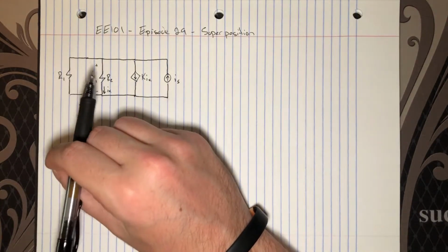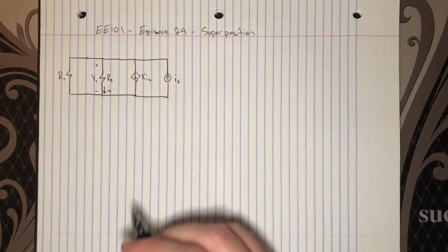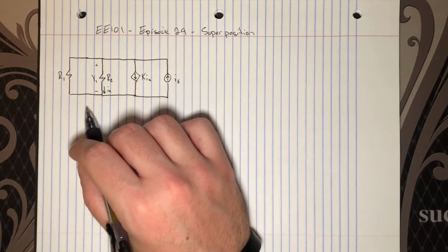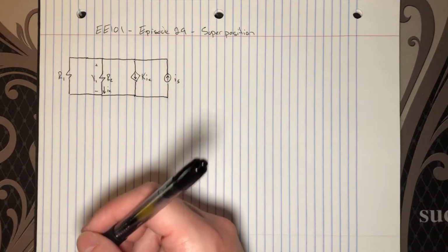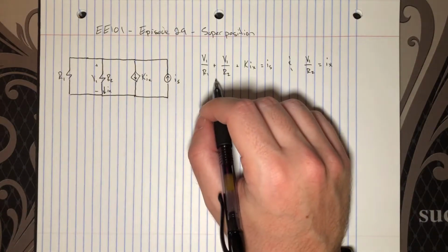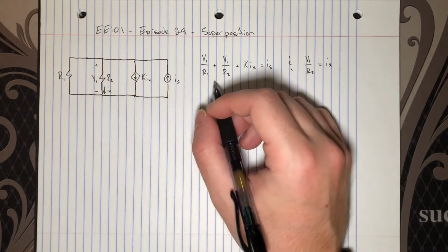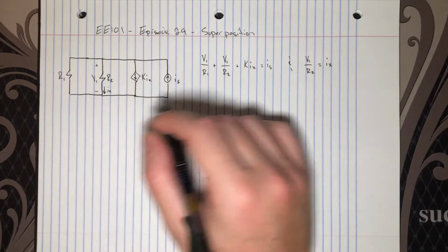I'm calling the voltage across R2 V1 because I'm counting up independent responses to sum via superposition for the total response. So for this first subvariant, I'm just going to call it V1, and in the next circuit I'll call it V2. So I'm going to solve for V1 in pretty much the same way that I did in the last example. We're going to do a KCL at this top node. Notice that things look incredibly similar here to our original case. It's just that the term involving the source voltage in R1 has changed slightly.